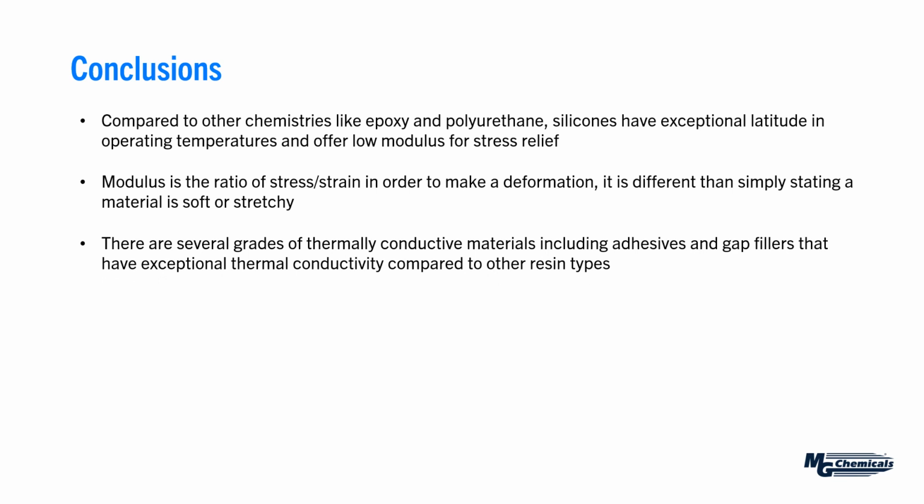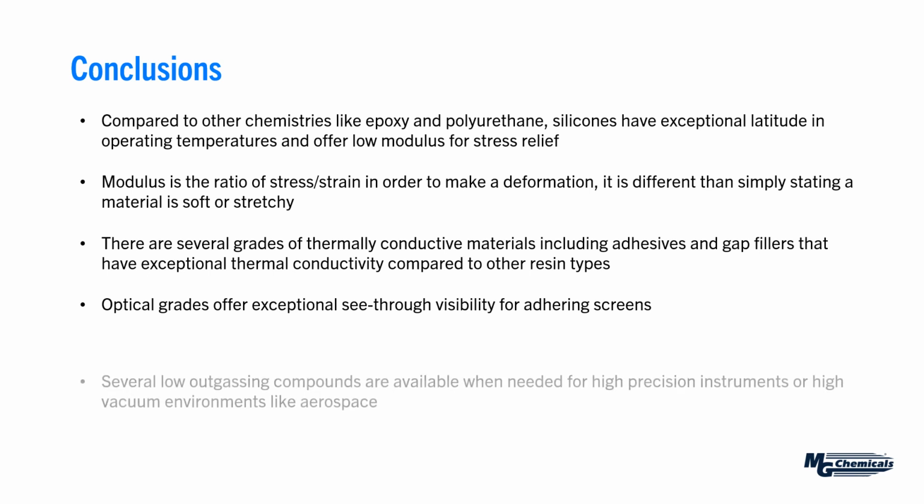There are several grades of thermally conductive materials, and these include adhesives and gap fillers. And again, they tend to have exceptional thermal conductivity. Some of them are pushing up to 10 watts per meter Kelvin, which does make them somewhat a superior material over epoxies and polyurethanes. Optical grades offer exceptional see-through visibility. And again, it's for adhering screens where you need that clarity.